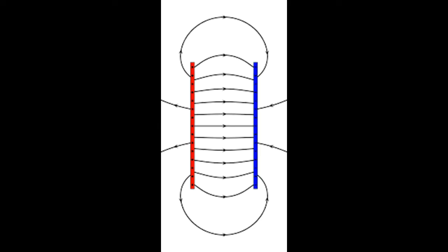As the water rises, it introduces a higher dielectric constant into the system than it was previously. Air having a dielectric constant of 1 and water having a dielectric constant of 80, the capacitance of the system greatly increases as we fill the tank with water.